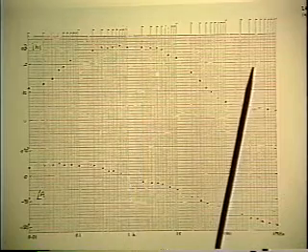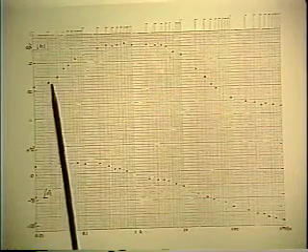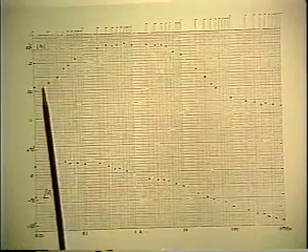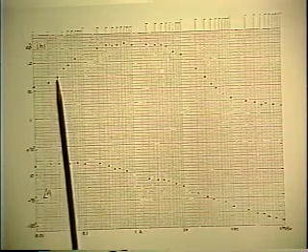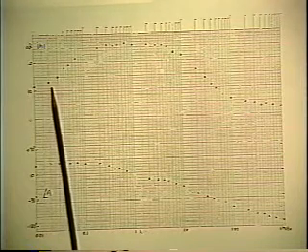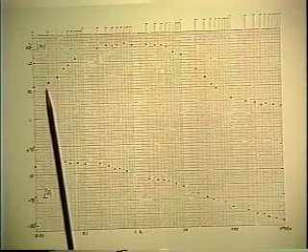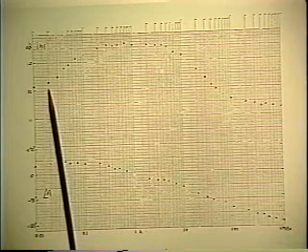All that's straightforward. If you keep on going down in frequency, then things get a little fuzzier. It looks as though the magnitude points are now beginning to flatten out again, which means you suspect that there is a zero down there, but you're not too sure, because there's only 1 or 2 points to tell you, and there's experimental error in there anyway.